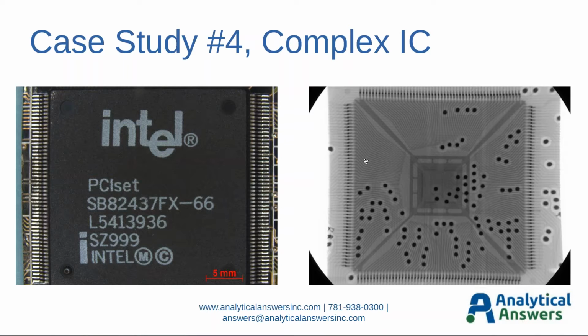We also can use real-time X-ray to document the sample in a non-destructive method. In this particular case, I'm using real-time X-ray to first find out where exactly the integrated circuit is located within this package. There may be one or more of these integrated circuits within this package as well. I want to understand that. In this particular case, there's just one. It's near the center of the package. We can see the corresponding wire bonds going from the integrated circuit out to the leads here, which were attached to the printed circuit board module.